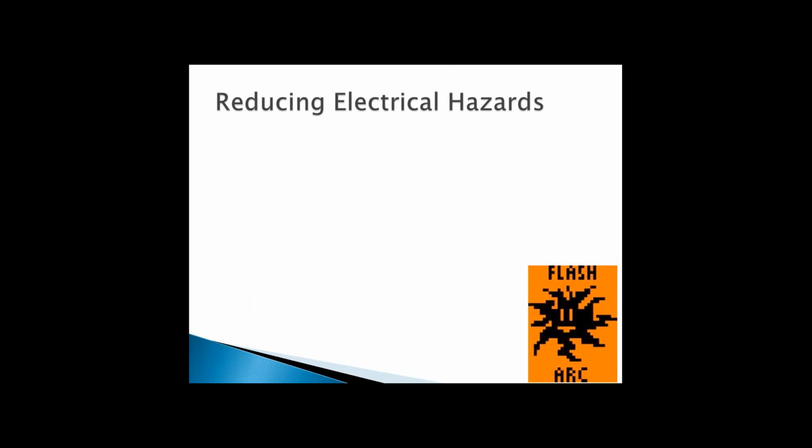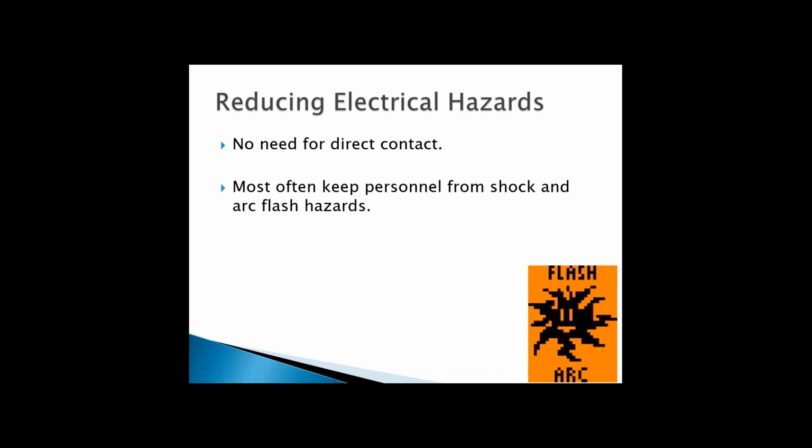One specific benefit from thermography or infrared technology is that you can reduce your electrical hazards. Well, how so? Well, you can inspect equipment without being in direct contact with it, which is pretty important. Most often, using this technology can keep you from shock and arc flash hazards, and you can perform an assessment of your equipment by being outside of an arc flash boundary.